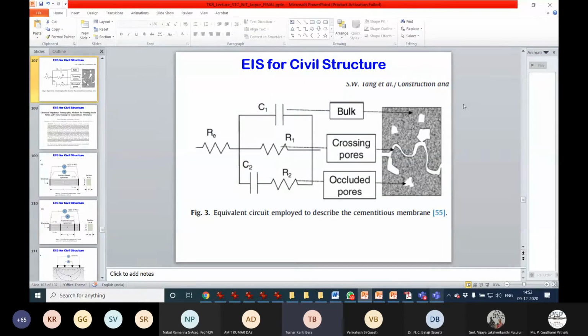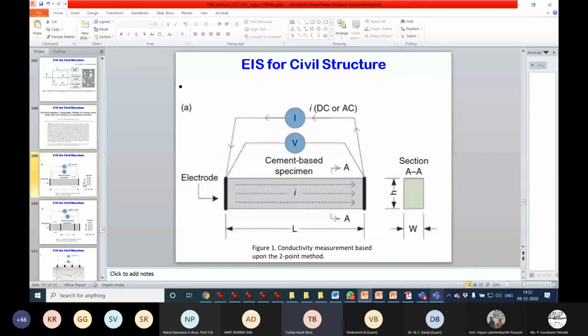Electrical impedance spectroscopy tells us about signal measurement techniques, and those will give us only a few data points. Means we will have some voltage or current or impedance at particular frequencies, say 5 or 6 or 7 values, and those can be plotted in a graph. From there we can get the equivalent circuit also, but it will not give us any cross sectional image. If there is any crack or void, that will only be visible if we have impedance tomography.